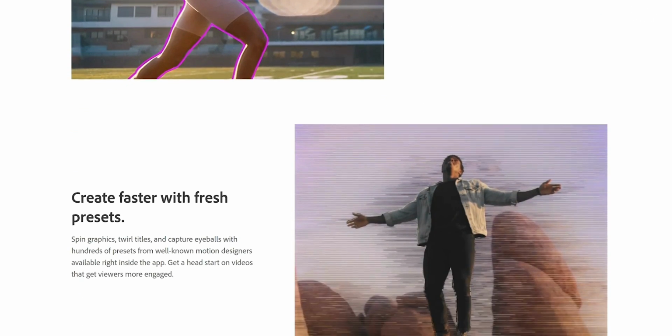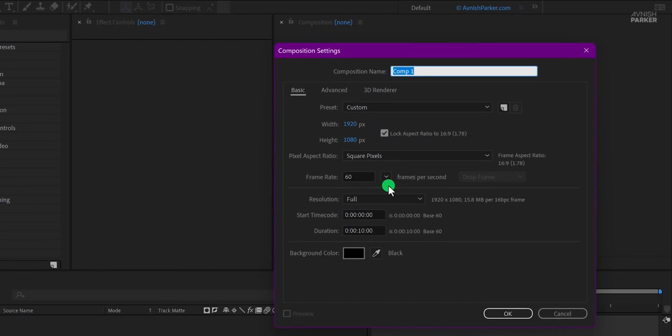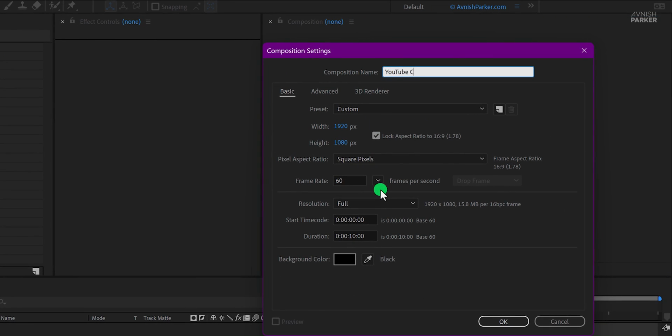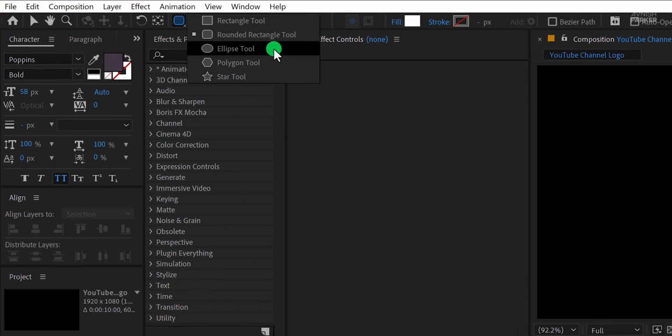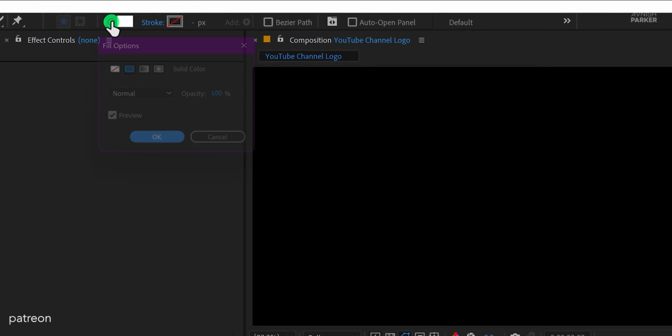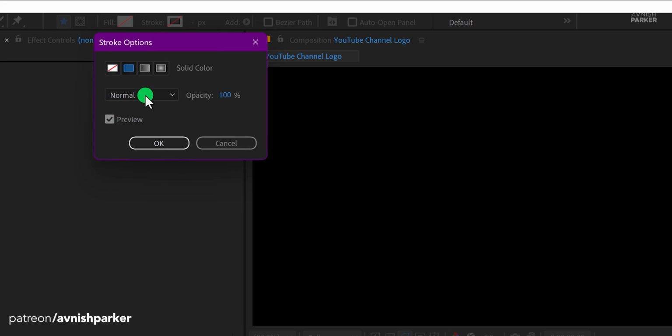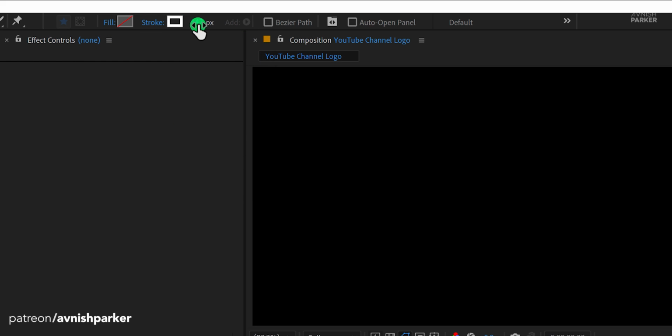Alright, open After Effects and create a new composition. I'm calling it YouTube channel intro. As always, I'm using the 1920 by 1080 resolution and a frame rate of 60. Hit OK. Then go to the tools and select the shape tool. I'm using this ellipse tool. Please note my fill is set to none and my stroke is set to a solid color. I'm using white for the stroke. Let's keep the stroke value around 25 pixels.